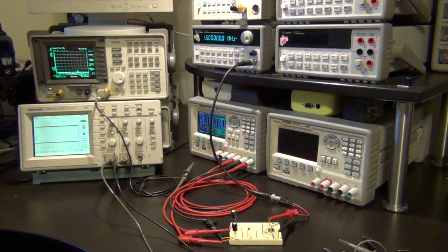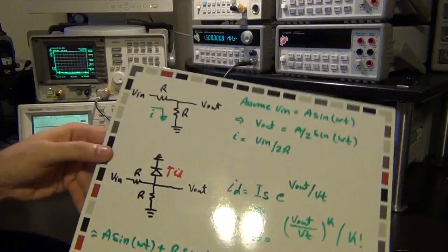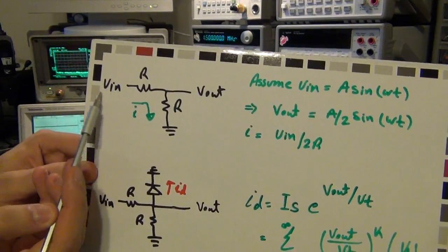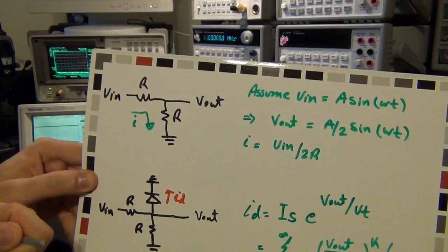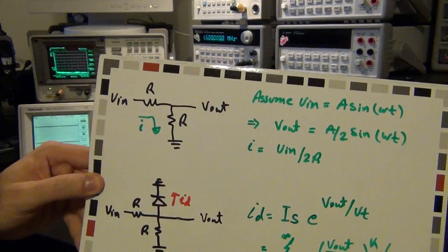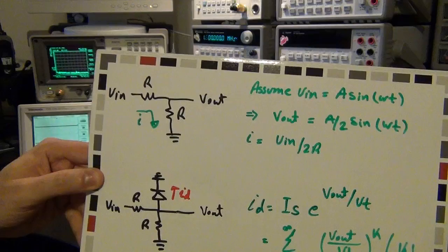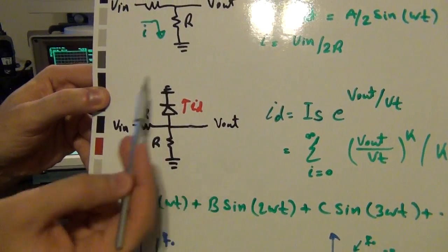And everything's hooked up and connected, and we're going to measure it. The only one thing that I've done is that here, instead of connecting my signal source directly to VN, I've placed an amplifier in the front that has a gain of 1. This is just a buffer, so for all of our purposes, we're going to assume the amplifier in the front is completely linear, and we're only concentrating on this circuit.